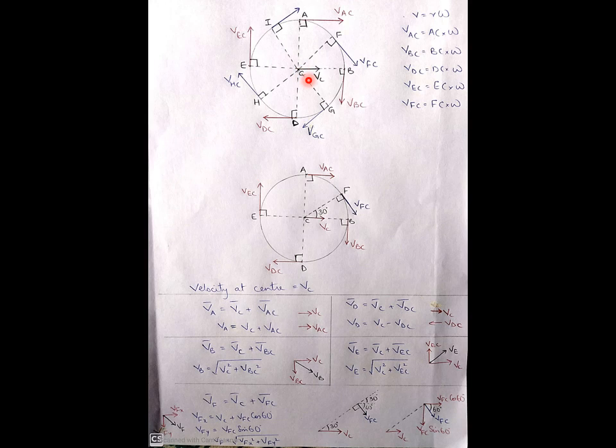And there is only a single formula to find it. To find the velocity, velocity is given by V equal to R omega, where V is the linear velocity, omega is the angular velocity, R is the radius. In this case, all the points are on the circumference, so we can say it as the radius itself. Or if it is not on the circumference, just assume that this point A is somewhere over here. So we can't say it as radius, so it is better to say in terms of this distance itself, which means if A is over here,